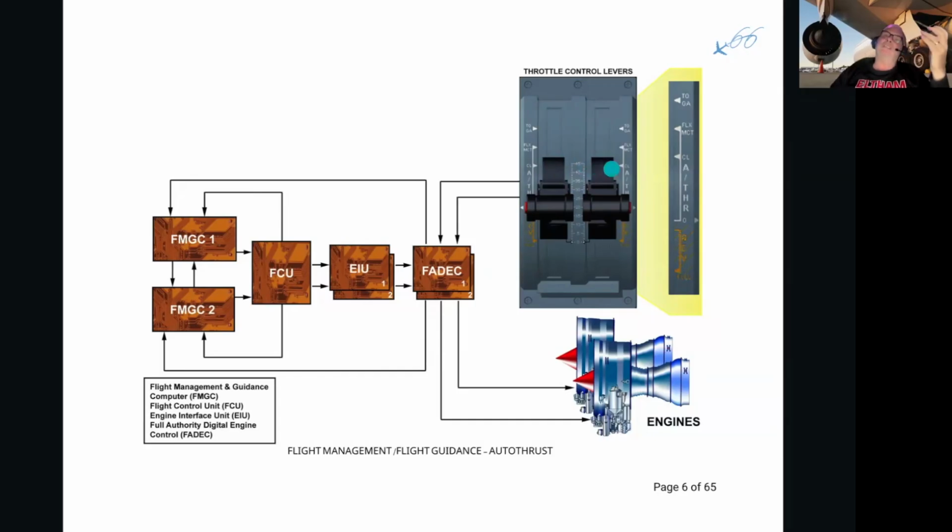We're talking about the auto thrust system in the non-moving situation, where the throttles are in the climb detent after the auto thrust is engaged and active. So the engines will get more or less fuel from all the systems, regardless of the throttle position, which will not be moved until the pilot has heard the command to retard, either just before or on touchdown.